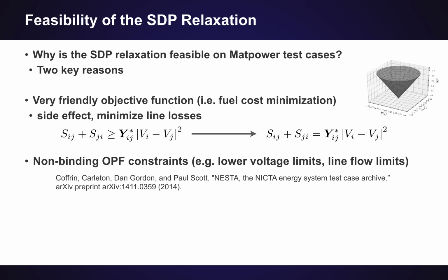And this is actually a big advantage for a convex relaxation, because when the constraints of your problem start to become important is when the relaxation will want to cheat and want to increase the line losses to do something tricky. And if they don't exist and you're really solving problems without all those OPF constraints, it's not clear that it's actually a hard problem anymore. Remember, those proofs of hardness were done with all the constraints in the original problem.